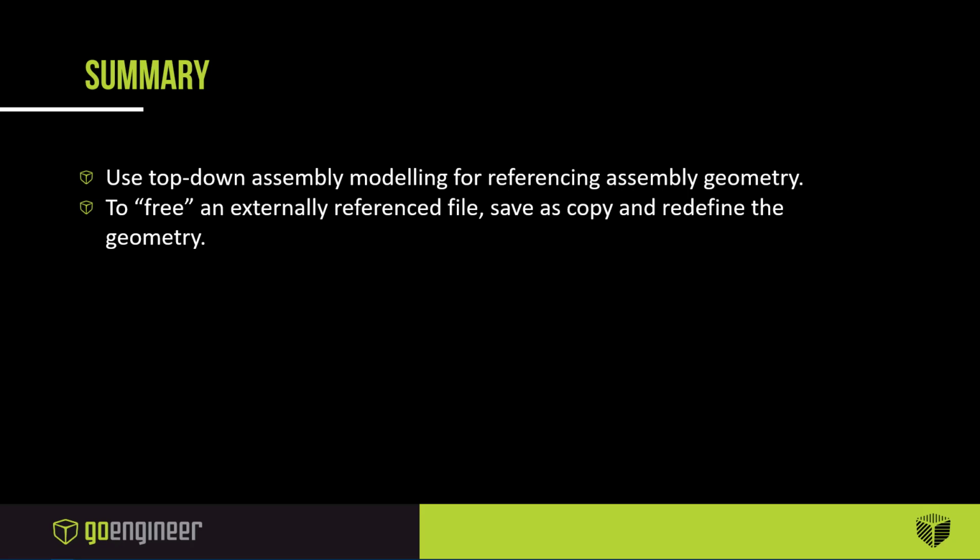Okay, when inserting a new part, what are the advantages of leaving external references and not just breaking them automatically? So it really depends on what you're trying to accomplish. I suppose you would immediately break any external reference if you know that you don't need it to update. You just want the visual advantage of looking at the assembly while you model with one and done dimensions.